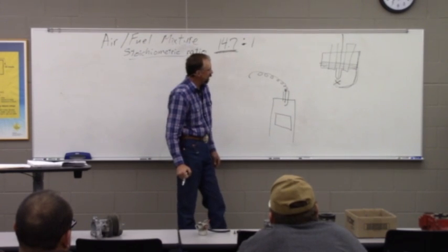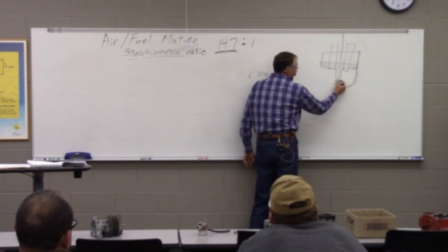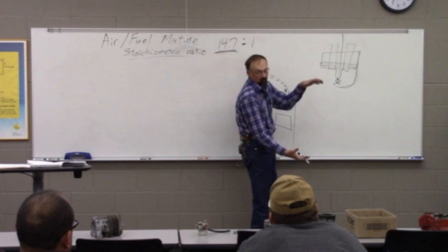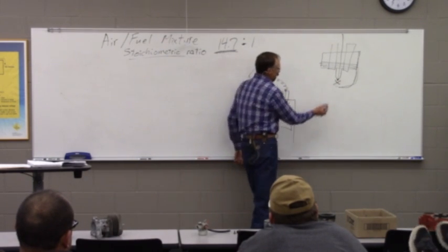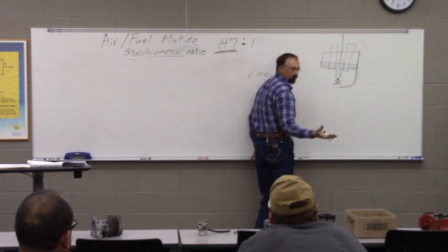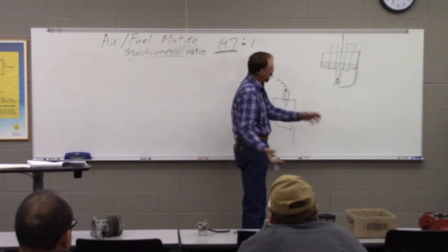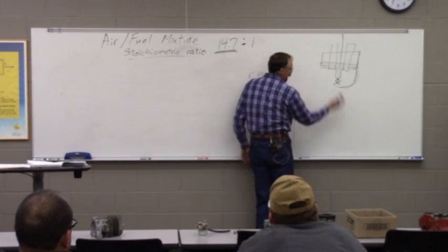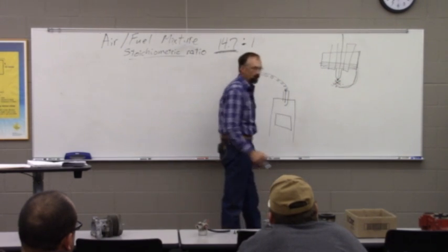When we're talking about voltage and amperage like we were before, remember, we've taken on our compression stroke and we've compressed our air. Compared to atmospheric pressure air, like what we're breathing here in this room, once we've compressed that, there's way more air molecules and some fuel molecules all in this space that actually inhibit the flow of electricity.